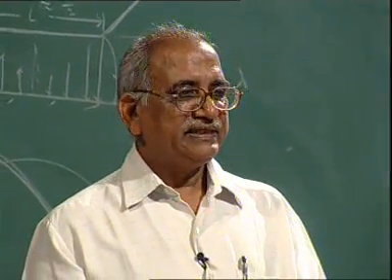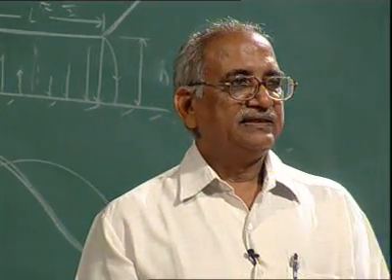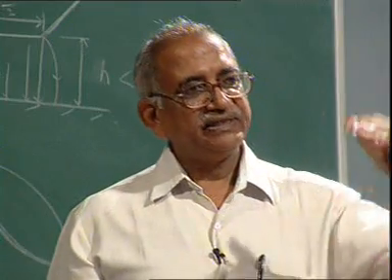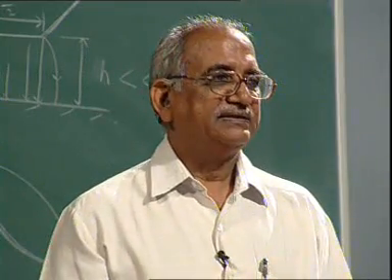And when we say TE10 mode, it means the field has halfwave variation along one direction, no variation, or it is constant along the other direction.